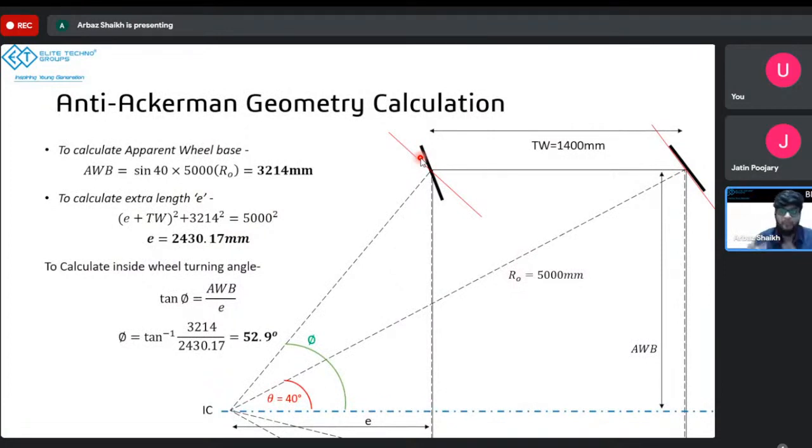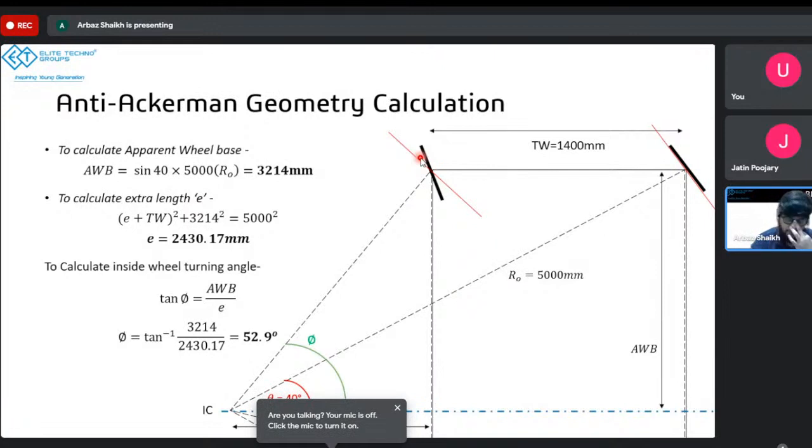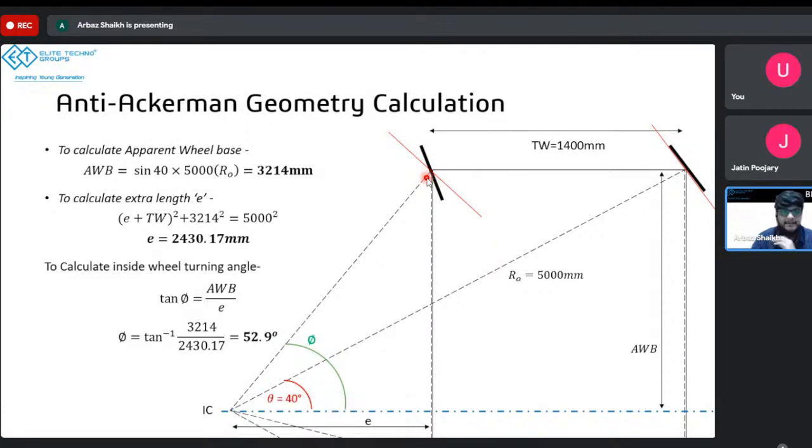After this, what they do, they have tire data, okay, which is very confidential, we cannot get our hands on that, but they have the tire data on different loads at different speeds at different turning angles. Okay, and that tire data is nowadays computerized. You just get a software by Pirelli if it's a Formula 1 race, and they give you these input parameters. You can put in the speed, you can put in the mass, you can put in the angle by which you want to turn, and it will output the slip angle for each of the wheels, right?